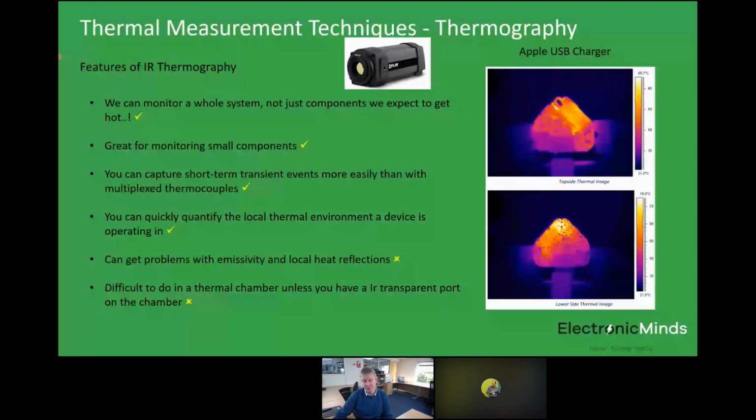Yes, it would do. So effectively, that 0.005 degrees C per watt would be from the metal of the cold plate to the inlet temperature. So anytime you've got further thermal impedances as you go back up through the stack to the physical junction of that semiconductor, the thermal impedance is going to rise. But what we're saying is that the cold plate itself is going to do a very, very good job at maintaining a nice low temperature, and then really the rest of the thermal behavior of your system is going to be largely determined by your power semiconductor package and its bonding onto that heatsink. That's not the case with a passively cooled heatsink, like an air-cooled heatsink. The heatsink temperature will rise significantly, whereas with liquid cooling, it stays very, very stable when you dump power into it, and that's quite a nice thing for cooling.